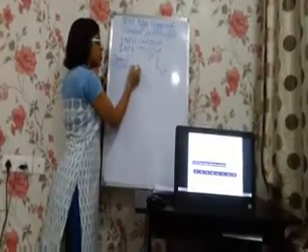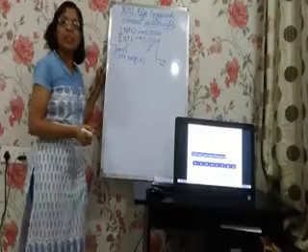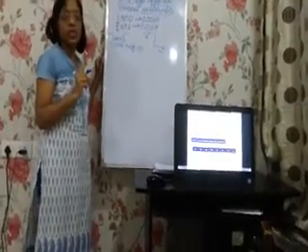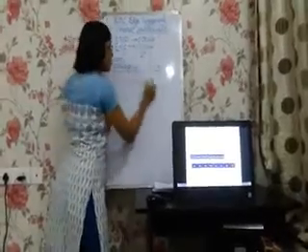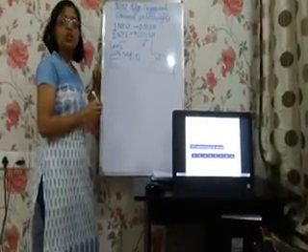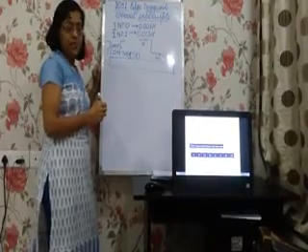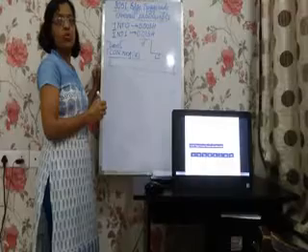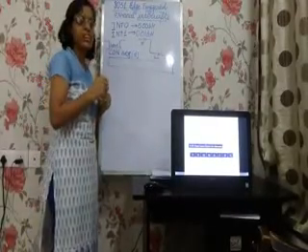This register looks familiar. We had used this register when we did the timer programming. This register consists of two parts. The upper 4 bits are used for timers and the lower 4 bits are used for the interrupt section. So let us see the lower 4 bits of the TCON register and try to understand these from this slide.